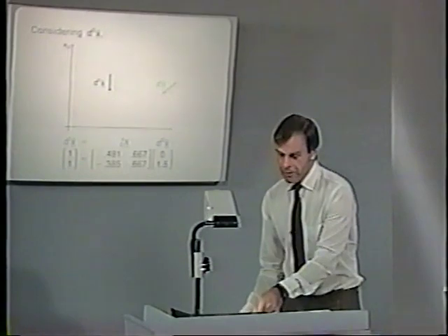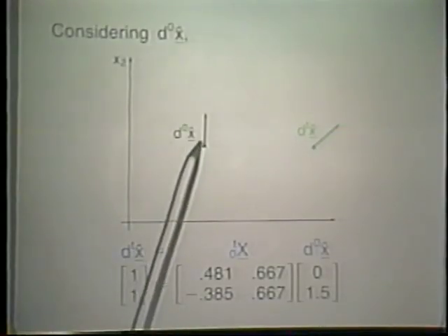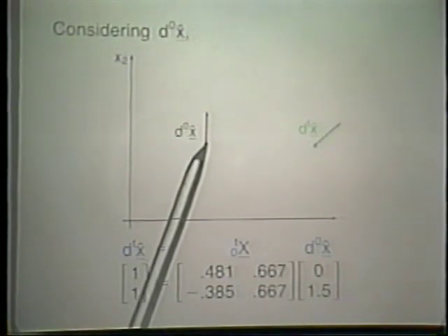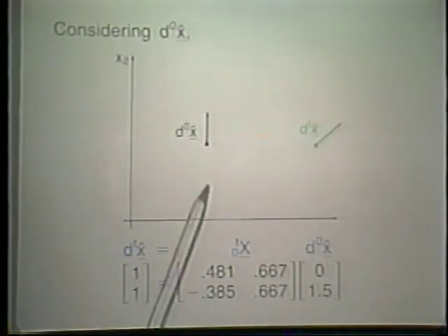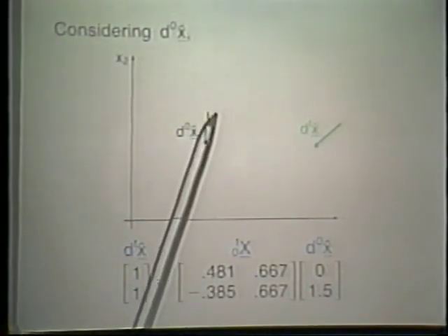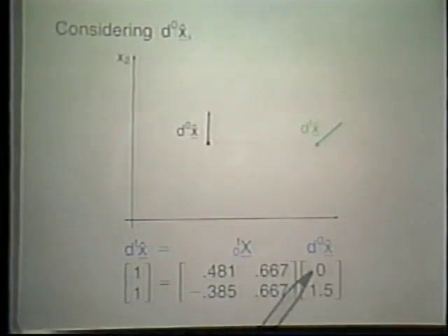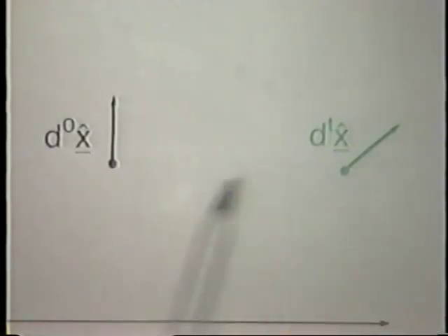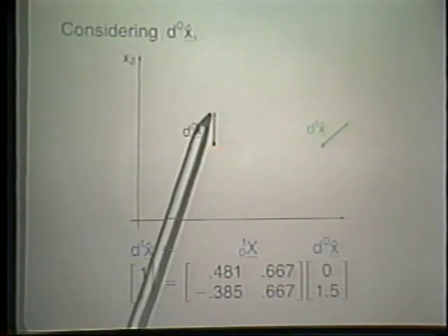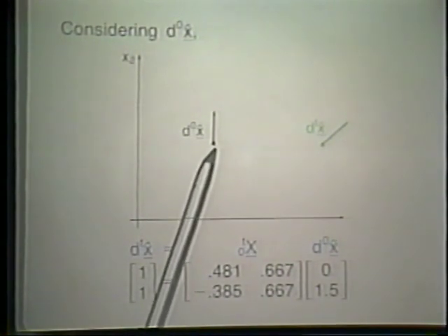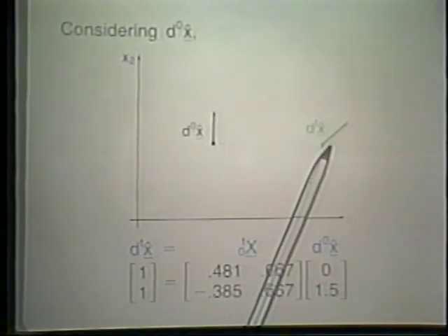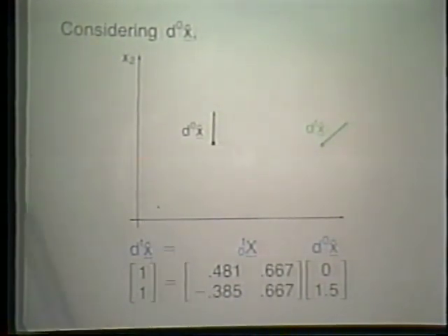Well, let's look at another fiber, the one that we had on the earlier view graph. Here, another fiber. And if we recognize, of course, that for that material particle here, the same material particle still, we still have the same deformation gradient, we can take the vectorial representation of that fiber as given here, multiply this out, and we directly find out what has happened to that infinitesimal fiber in the motion that we are considering. Notice in this particular case, the components of this fiber are 0 in this direction, 1.5 in that direction, and it has moved to here and has taken on components 1 and 1 in each of the coordinate directions.